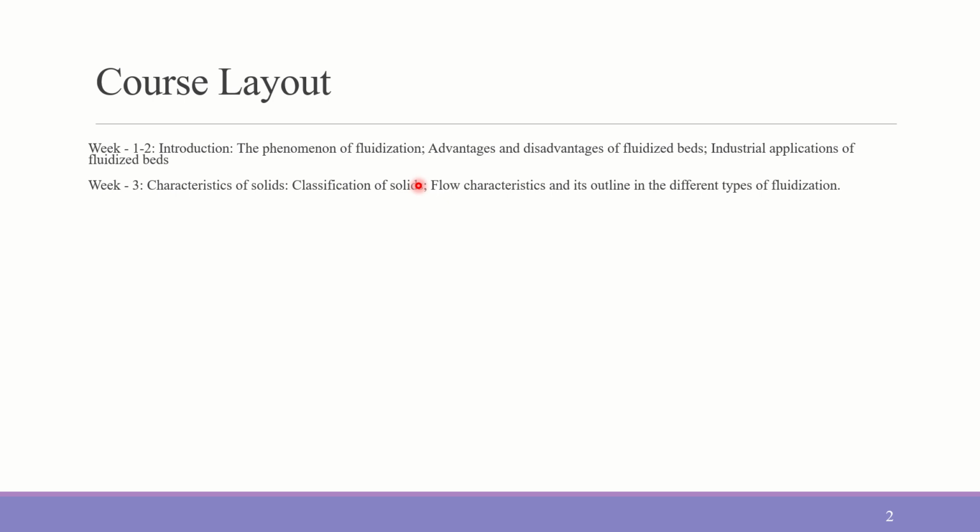Later on we saw the classification of solids, because we have seen that Geldart classified the solids into four categories: A, B, C, and D, depending on their size and the relative density between the fluid and the particles. Each class of particles behaves differently inside fluidized beds. Those things also we have seen.